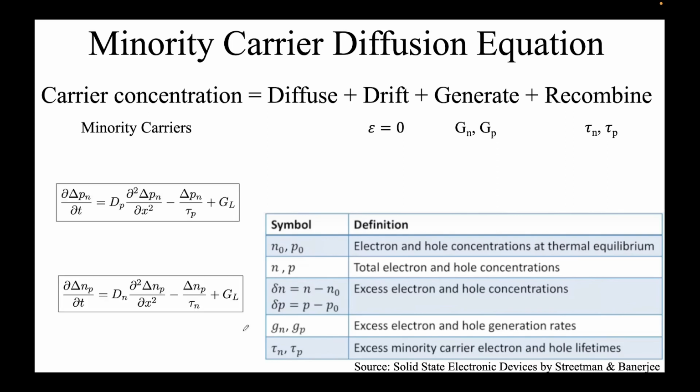Okay, so now I have replaced the diffusion term here. You can see the diffusion constant Dp coming, right? Secondly, I've also replaced the generation term. You can see it's the same, GL and G, it's here. So this symbol means p, and we're talking about holes here, right? In n denotes n-type semiconductor, p means the concentration of holes. So this GL in fact will be nothing but Gp in our case, because we're talking about holes, and in this case it will be Gn. So the top expression is for n-type, the bottom is for p-type.